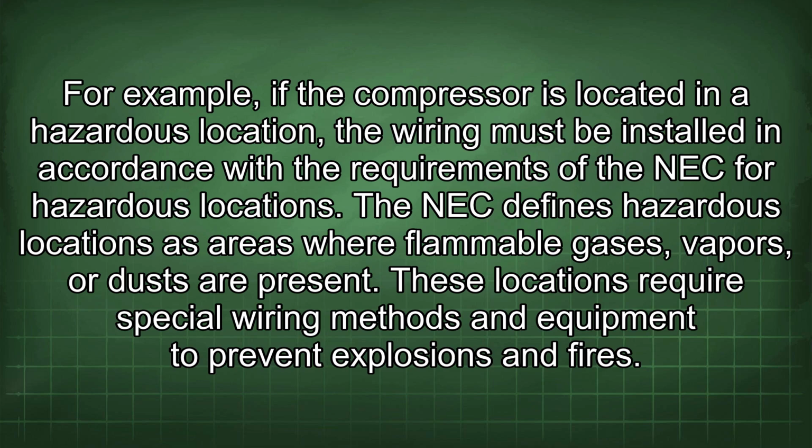For example, if the compressor is located in a hazardous location, the wiring must be installed in accordance with the requirements of the NEC for hazardous locations. The NEC defines hazardous locations as areas where flammable gases, vapors, or dusts are present. These locations require special wiring methods and equipment to prevent explosions and fires.